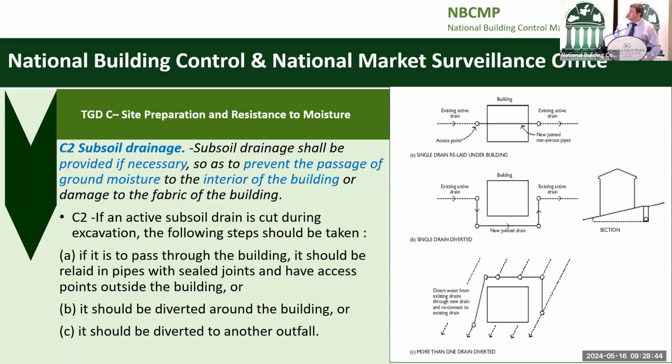Subsoil drainage, and this is really because years ago there were land drains put into existing fields, and stone drains and things like that, and they need to be diverted. That water needs to be collected and diverted into a proper water course when you're actually developing a site. And they're very practical, you know. You don't need more water around your development. It's only going to cause damage to the foundations and the structure.